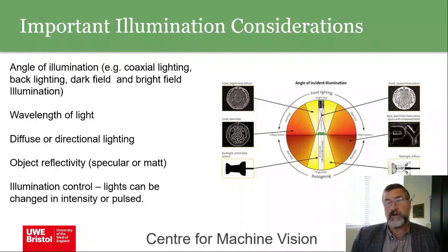Dark field illumination is very, very similar, but you look just away from the light source, just off the light source, and then any defects on the surface will appear as white marks because the light's been scattered. And these are standard techniques that are good for very light scratching on surfaces that's otherwise a bit difficult to see.